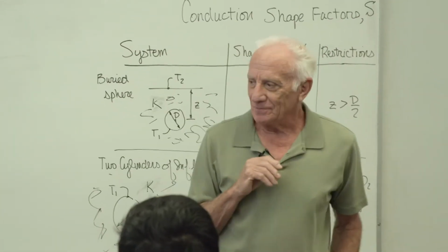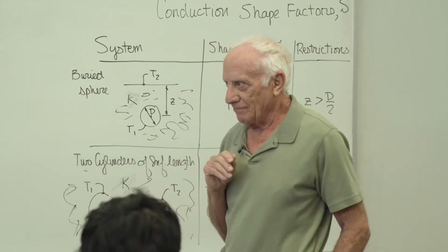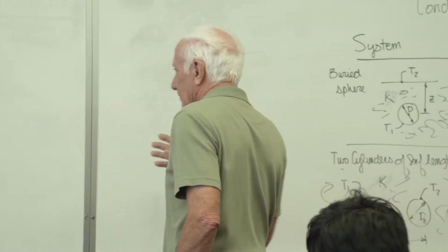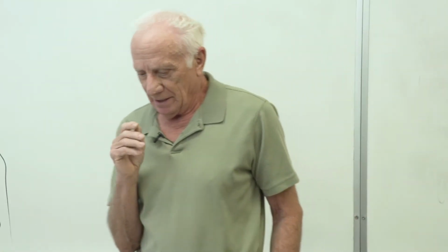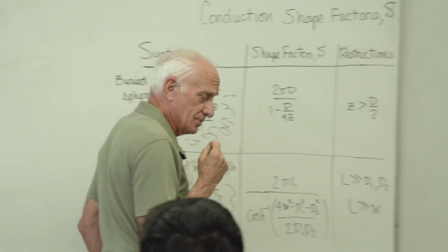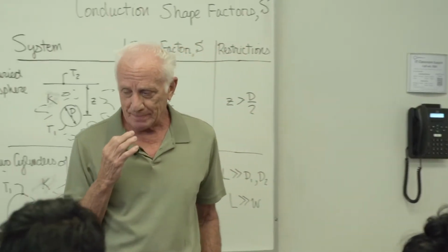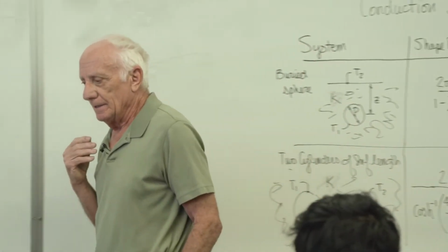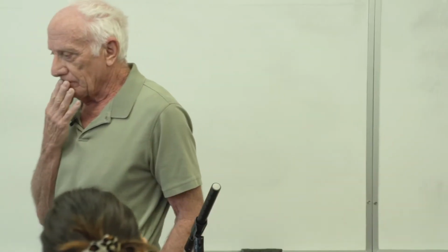As we said, we're in chapter 4. We'll finish chapter 4 on Monday. Where we left off last time, we were looking at heat flux plots in conduction heat transfer. What is a heat flux plot? A heat flux plot is a graphical diagram of the heat flow lines, called adiabats, and the constant temperature lines, called isotherms. There are several rules you follow when you construct them. We went over those, and we'll do one more today.